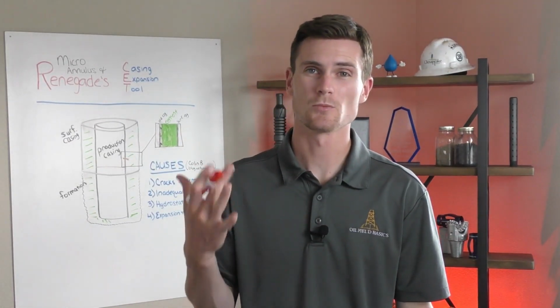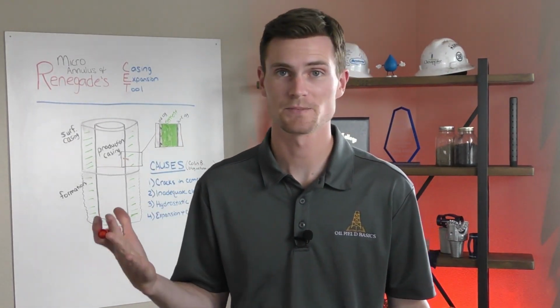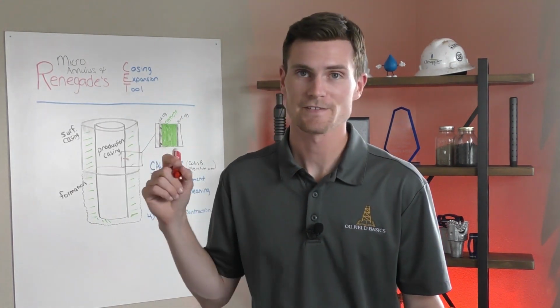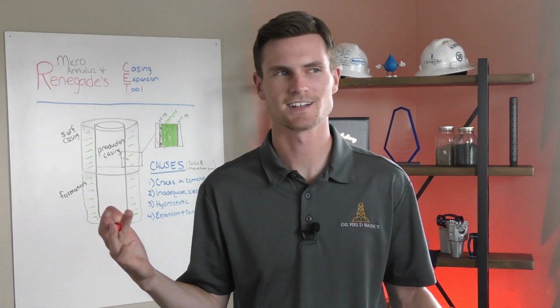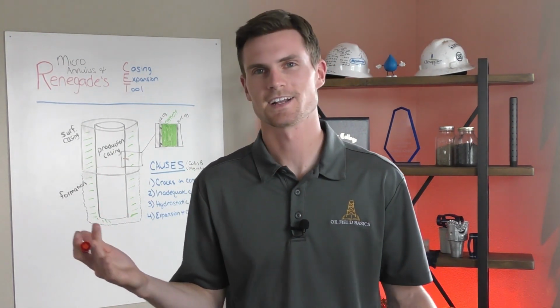No ID reduction, no sacrificial parts, we're not leaving anything behind. Fully reusable, we can apply as many crimps in a well in one shot as we may need to. The other critical thing too is that it is done at normal well conditions, so you don't have to pressurize up your well to take care of this issue, because if you pressurize it up, then you can risk sealing off the microannulus and then not having anything to pump into anyways. So kind of stabbing yourself in the back.